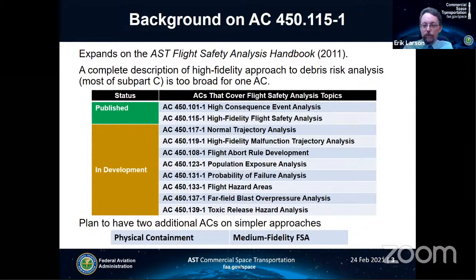There's also a plan to have 2 additional advisory circulars that are going to be talking about simpler approaches to accomplishing flight safety analysis. The high fidelity analysis is not the only way to meet the regulation. Recognize that smaller vehicles pose less hazard or can be contained to certain areas, you still need to meet the core risk regulations and the hazard area analysis, but that doesn't require the level of fidelity or detail to demonstrate compliance with those. And so those ACs are also in development, but other approaches that also could be simpler but still meet the requirements are also possible.